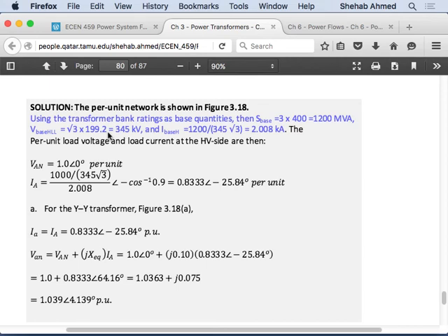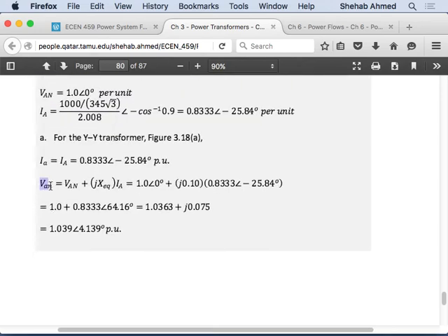The single-phase voltage base, remember, now it's all confusing. So now the line-to-line voltage base is 13.8 times square root of 3. But I calculated the phase voltage in per unit. For me to calculate the phase voltage in actual values, I have to multiply it by the phase voltage base. If I'm doing my calculations in line to line quantities, using the line to line voltage base, then I find the actual value by multiplying by the line voltage base.